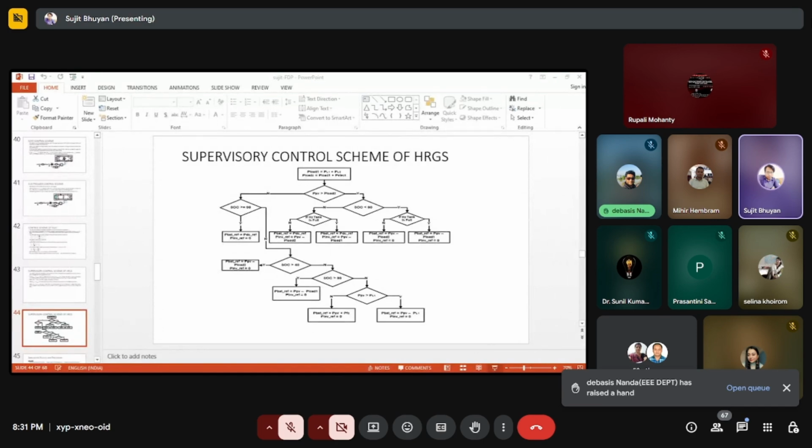This is the DC bus voltage. I always tell you, the DC bus voltage is practically not constant. It varies a little bit. Previously in the simulation models I described, the state of charge is more than 90%, or between 90 and 30 or 25%. When the state of charge is less than 30% or 25%, see, the SOC level decreases rapidly. At that time, the battery is also not fulfilling the required amount of demand.